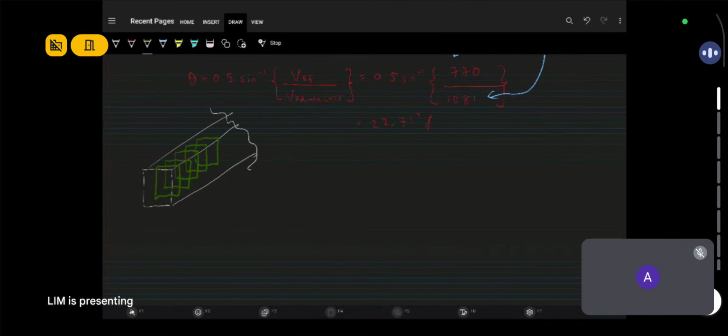What they're saying is these steel bars are H12, meaning 12 mm diameter bars, at 175 centers or spacing.